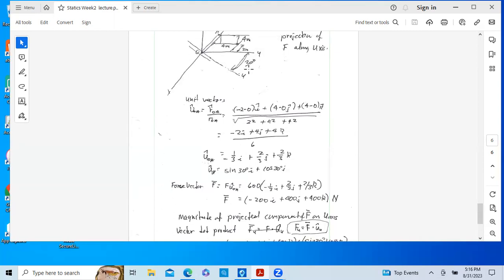What you can do with this now, since you know the force, there's a little centerpiece of steel in here. It's attached to this outer ring. You're going to design for this centerpiece. You now know the force acting along the axis, 246 newtons, and now you can design it. And actually, it's a pretty simple design. Once you pick the material, there's a strength of materials, that's the class.